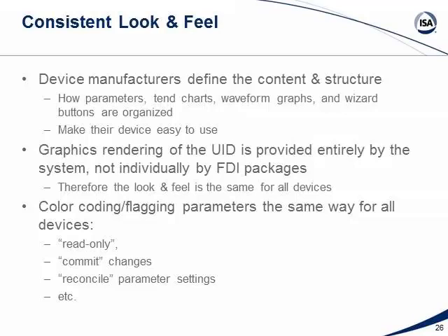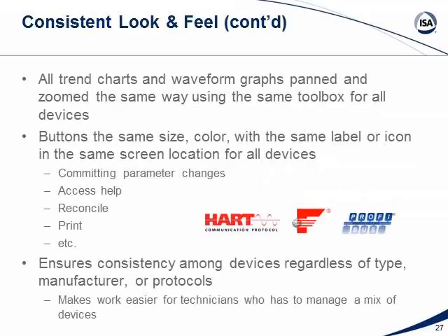But on the system side, obviously it does the background work to take the process variable out and put that on a trend screen, for example, or a graph or a waveform, or maybe you're visualizing a valve signature that you might want to compare from a previous stored valve signature to see if you see any degradation in the quality of the equipment, for example. So the nice thing about EDDL is that control is managed by the system level.